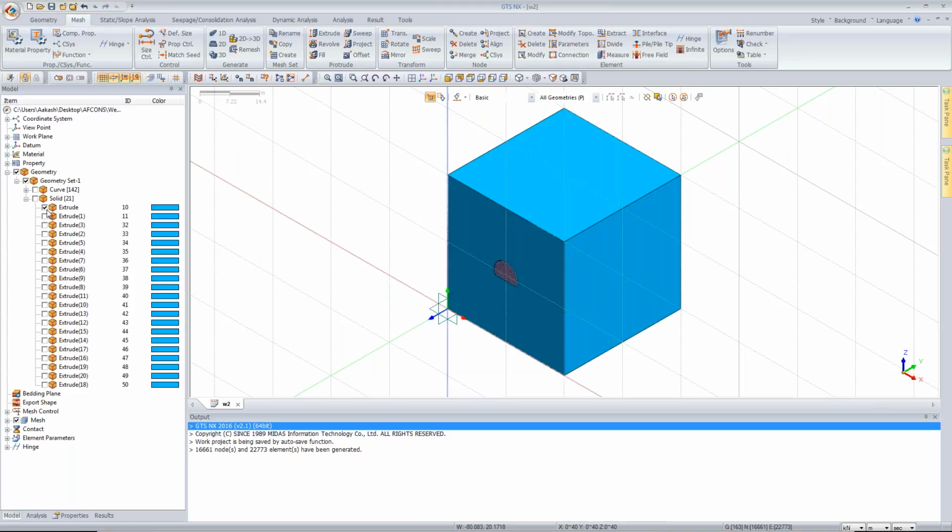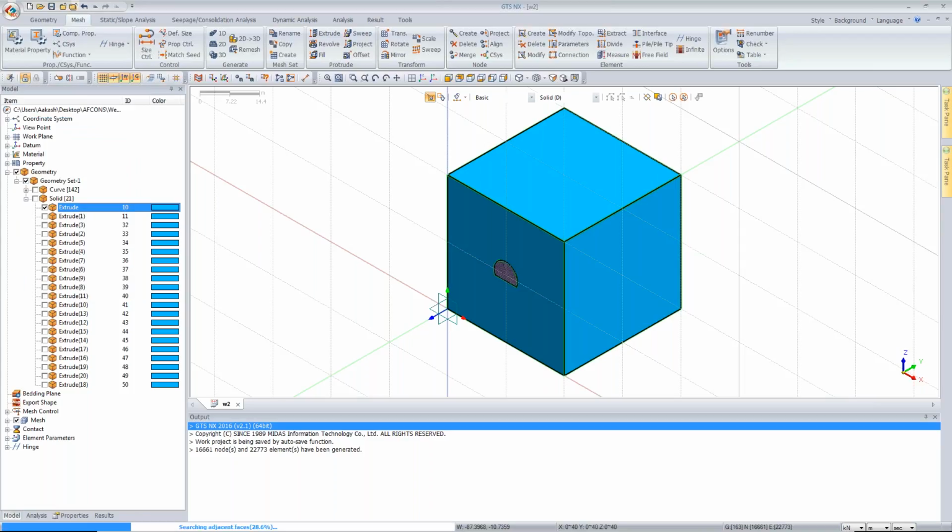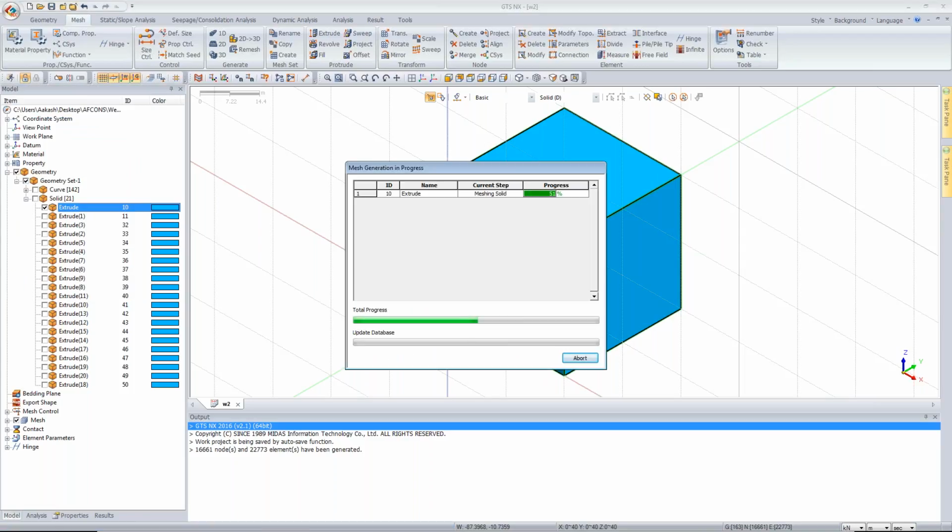First, let's just mesh the solid. So once again, 3D mesh. Even if you give the outer solid a different size, you need not be worried, unless you keep the mesh the same, of course. You just give it a name, main ground. Just say okay. So hybrid mesher gives you hexahedron elements. It gives you a more structured mesh, as already discussed.